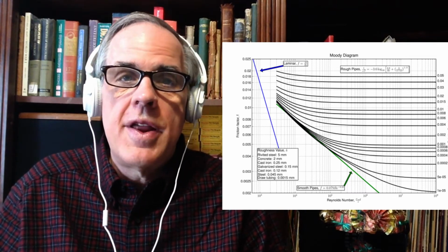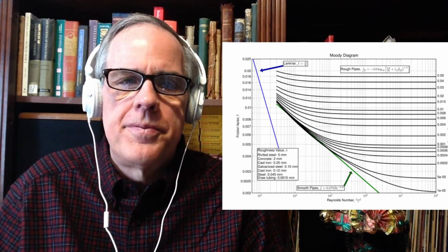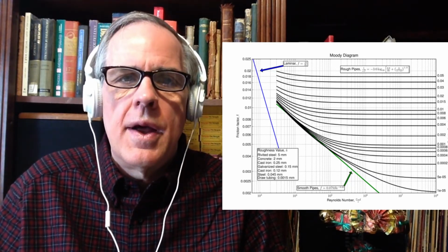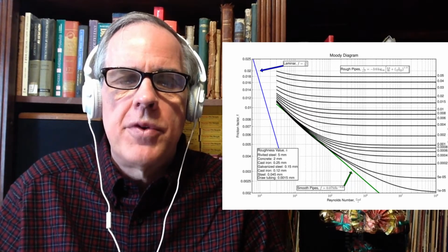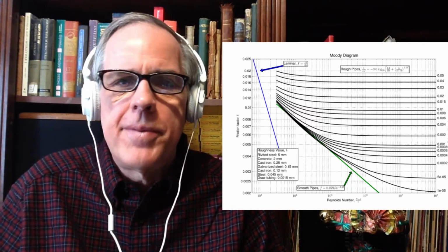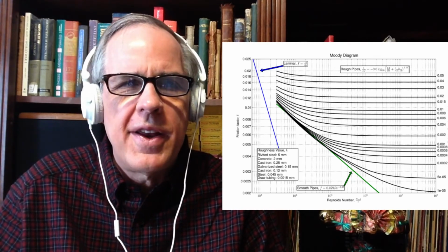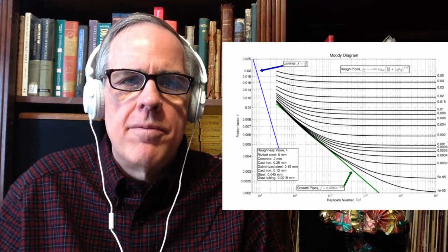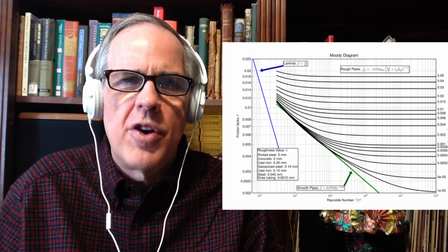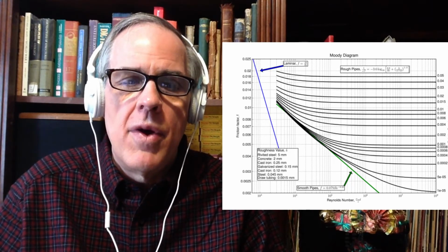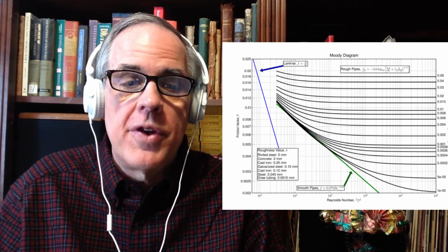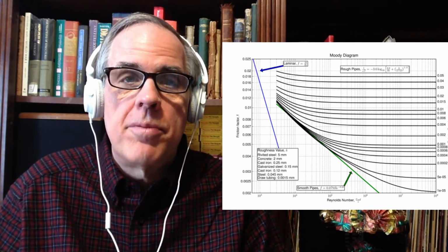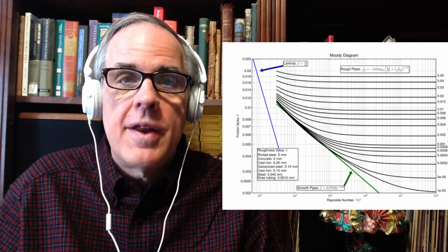For Reynolds numbers in the very low stages, flow is laminar, and it's very easy to compute the losses, up to a point. And then there's a transition period, and some charts have it gray shaded. And then there's the turbulent part. We're going to concentrate on the turbulent part. Most flow you get in practical applications is turbulent. If it's laminar, then it's pretty slow. By the way, speaking of laminar flow in closed conduits, human blood runs through our bodies with laminar flow.